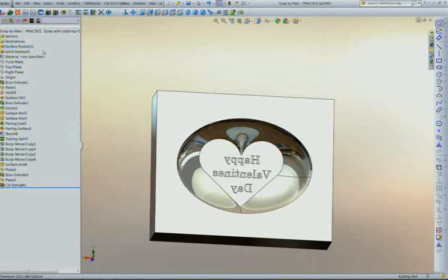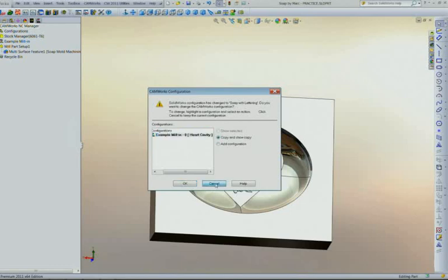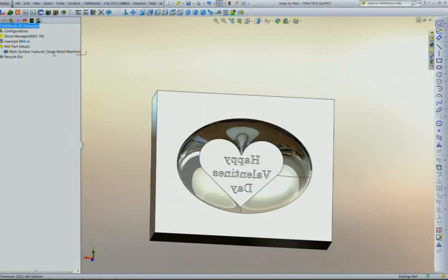So here's the SolidWorks feature tree, and in there you see you have bosses. There's a boss extrude there. You have all sorts of things. But when you look at the CAMWorks feature tree, which are manufacturing features, it's going to look different. In this case, it's looking at this as a pocket machining or a milling operation. So that's a multi-surface feature here.